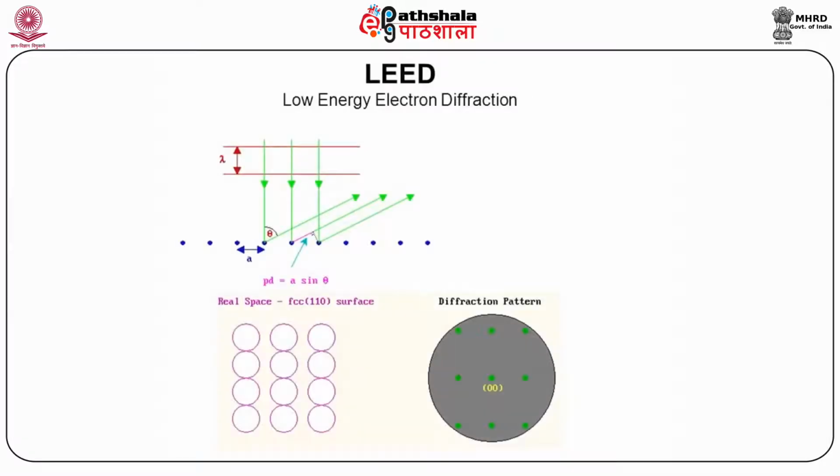We can, to a certain extent, control the defect structure and defect density of the layers grown by controlling the lattice mismatch. Three techniques have mainly been used for this purpose. The simplest one makes use of the fact that a metal single crystal may be oxidized and a more or less well-ordered oxide film is formed. In the case of nickel oxide and cobalt oxide, thin oxide films can be grown by the oxidation of nickel and cobalt single crystal surfaces.